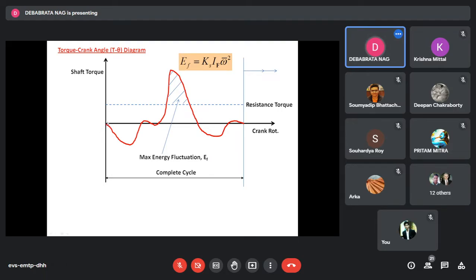That means from suction to exhaust, and during that there could be variation. And why does this variation take place? The answer lies in the inherent mechanism that we are going to use here, and that mechanism is the crank connecting rod piston mechanism. Why this variation looks like this, etc., we will discuss in our dynamics of machines class. But we can't avoid that non-uniform supply torque at the crankshaft.